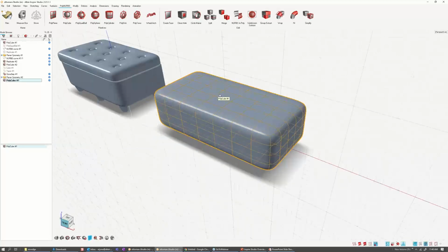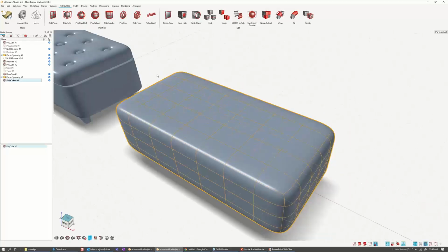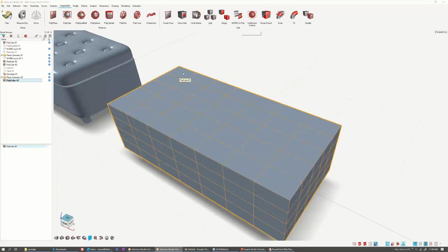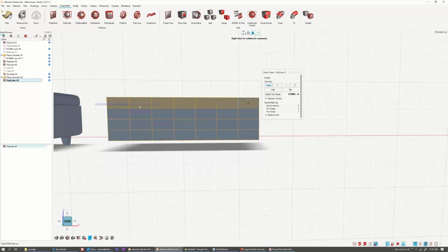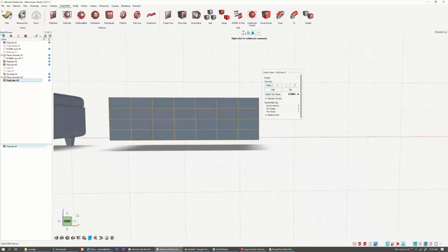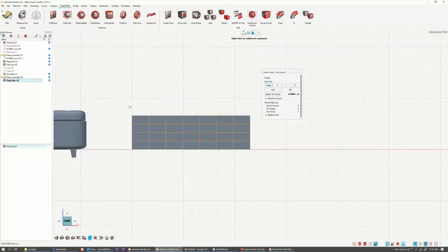So again, I have the surface, and I can use this as a building block for the next one. So what I mean by that is I'm going to go to N. I'm going to hit D on the keyboard. I'm just going to select all of these, so that I select the top faces, and I will hold Control. So let me go to the front view. I can just select these ones and deselect the ones that I don't like.